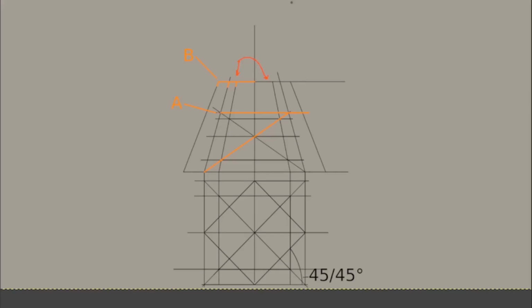Then this distance can be doubled and then divided, or a line can be eyeballed here in between the line of the unrotated square and the line of the bounding box for the rotated square. The amount of accuracy in this step will determine the accuracy of the height of the cube. The converging line in between was started at the projection, and the placement of its far end was estimated. Drawing a line between two near lines makes this easier.